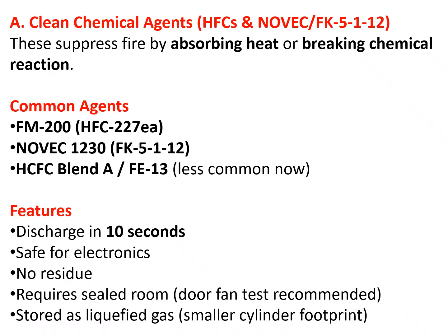The characteristic features of these agents are they discharge in 10 seconds, safe for electronic equipment. No residue will be left after applying this total flooding system. Requires sealed room. Door fan test recommended. Stored as liquefied gas that leaves smaller cylindrical footprint.